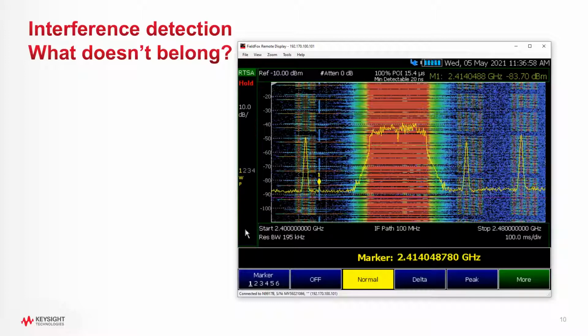It may fall in the middle of the Wi-Fi spectrum. So while it's not in general affecting things, if you have a lot of Wi-Fi traffic, it's going to be using some of the spectrum and causing interference. So you might see data rates go down. We're looking at that signal right now at this moment in time. We don't know anything about that signal. Maybe at certain times of the day, it becomes a really strong signal.